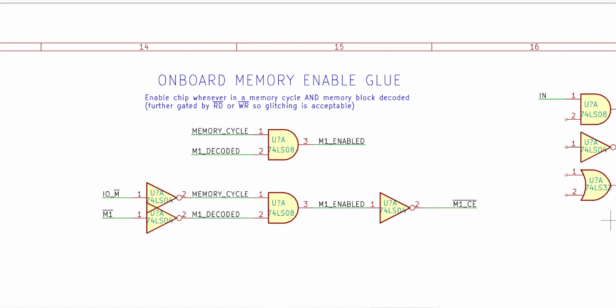And that gives me the zeroth version of that glue logic. And you can see that if I have a bunch of spare AND gates and a few spare inverters, this may be the preferred configuration for that logic. But with those inverters on the inputs and the outputs, it cries out to be DeMorganized, where it becomes an OR gate. So let me DeMorganize that, make that into an OR gate. I'm going to copy this, paste it, and then DeMorganize it.